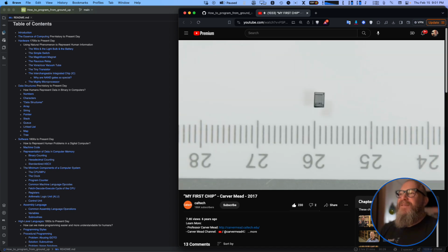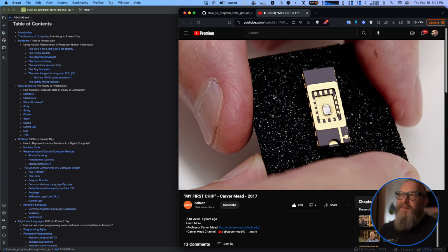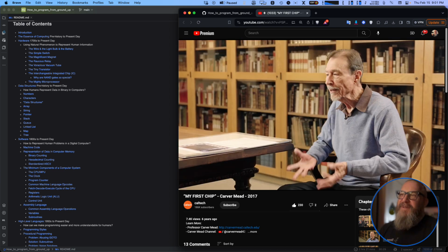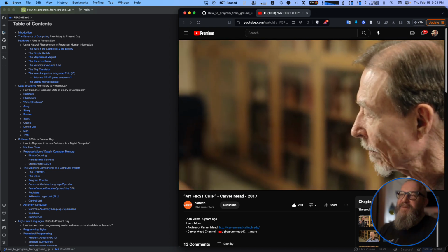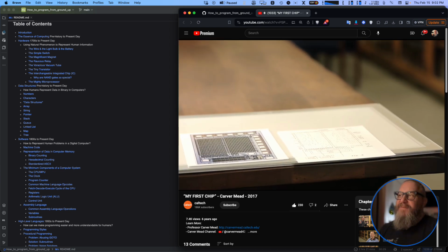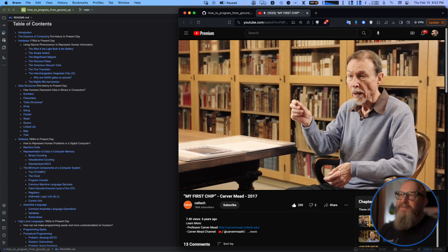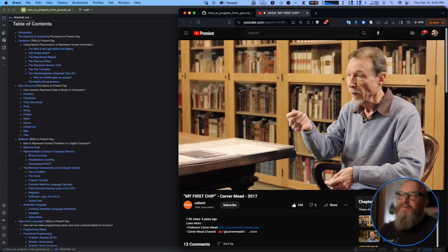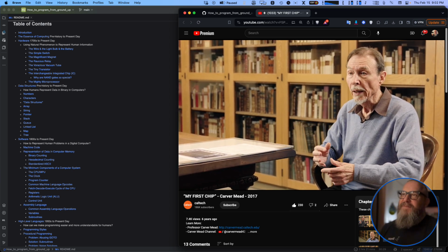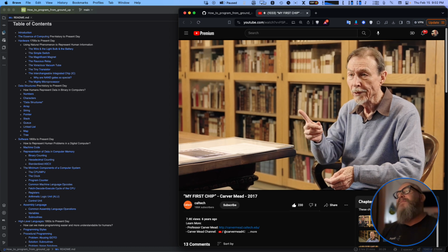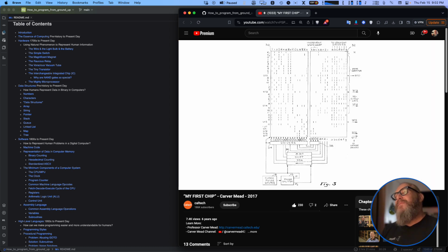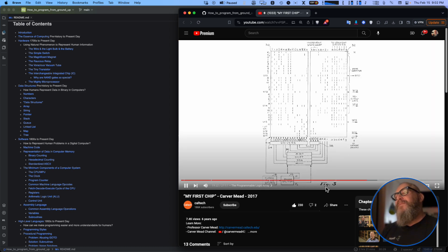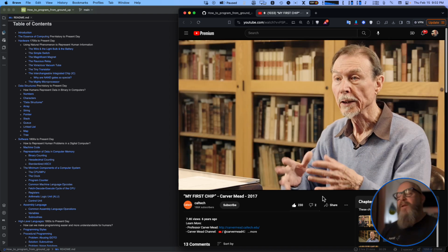Just for scale, I should show you what these chips actually look like. In order to have some illustration that made it clear what it was doing, I decided to program this thing to be a 12-hour clock. So it would display the seconds, 0 up to 59, and the minutes, 0 up to 59, and then hours, 1 up to 12. Because it's a general logic function, it doesn't care that there's a special case for 12 and 1 and all of that. It was just all built in the code. That's what all those ones in there are. They're taking care of the entire sequence.